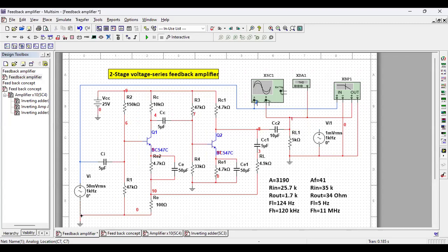So you see, negative feedback. I have shown you an actual circuit. So now you should believe in the theories and you should also believe in me that the gain reduces approximately by the feedback factor beta or 1 plus A beta. Gain reduces, but all parameters of the amplifier, it improves on the desired side, right? So this is how a feedback amplifier works.